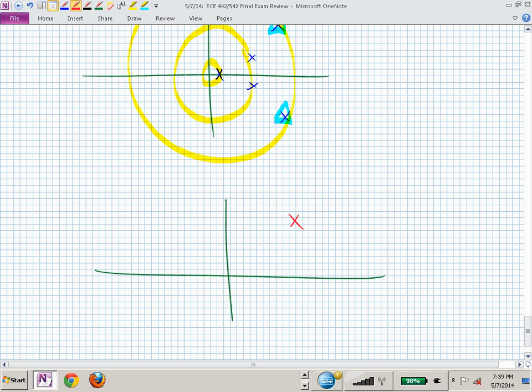If you had a transfer function and you allowed complex coefficients, then you could have a single complex pole. But we usually have real coefficients in our transfer functions, don't we? So those real coefficients are forcing, anytime you have a complex pole, you have its conjugate.